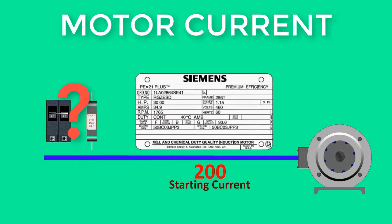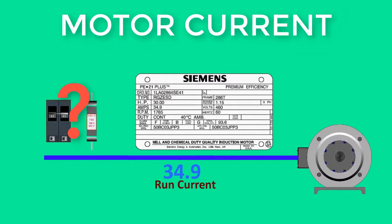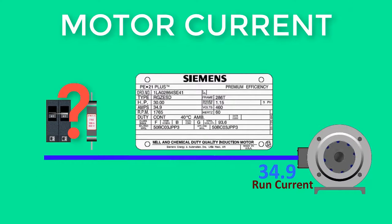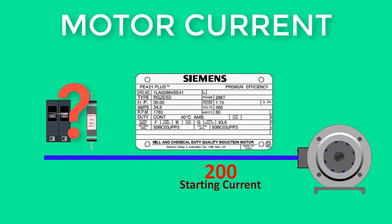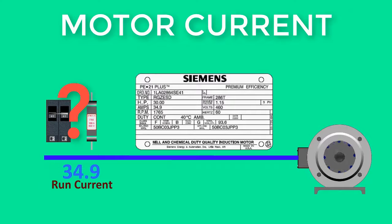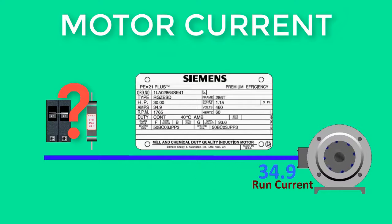In the example, the motor nameplate identifies the current at 34.9 amps. A breaker or fuse to the motor may fail if not designed with the starting current in mind. On the other hand, a breaker or fuse size that allows for starting current may allow excessive current to the motor after the initial startup.